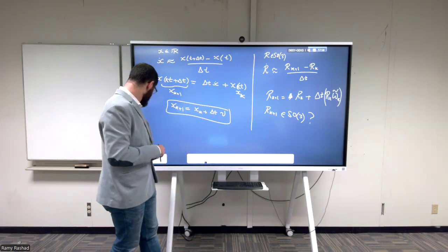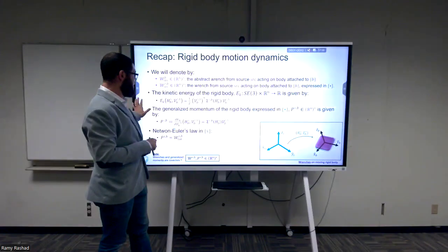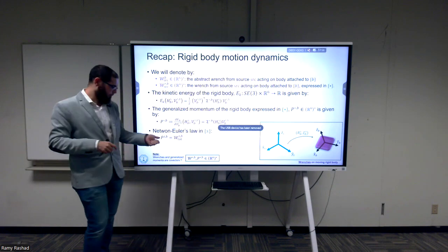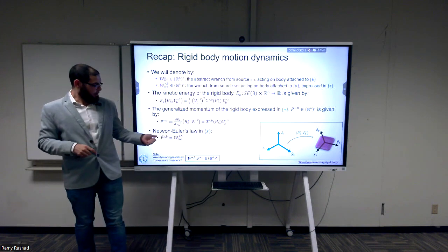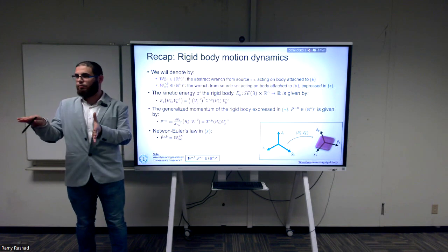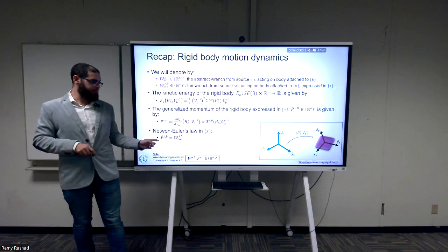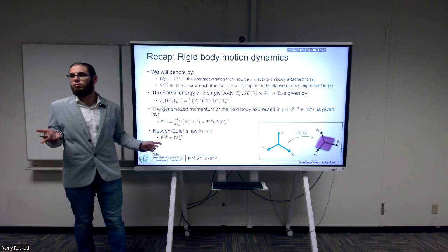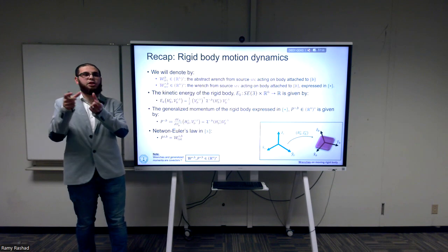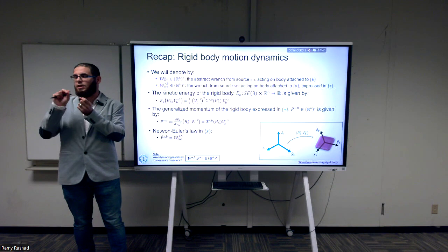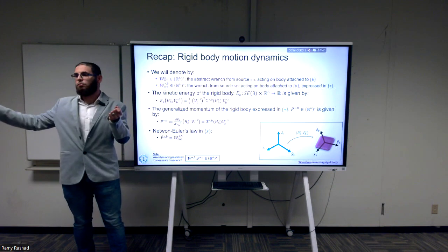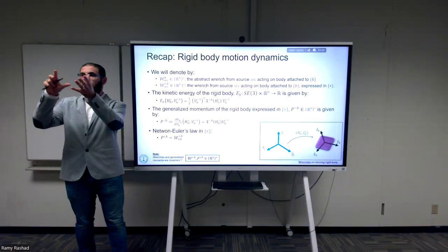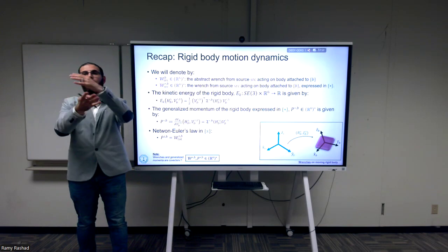Let's go back. Yeah, let's take this guy. If I do an integration on the computer and I don't apply any external wrenches, what do I expect of the generalized momentum? The P dot should be equal to what? To be 0. So if I start with some initial momentum, what should this number be throughout the whole simulation? Constant, right? If I start with some initial rotation, for example, and some motion, this body should drift around without changing this momentum, okay?